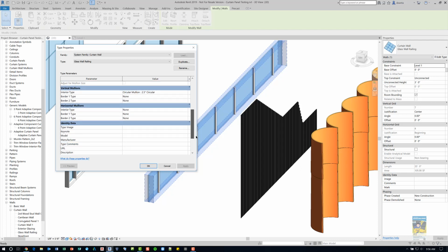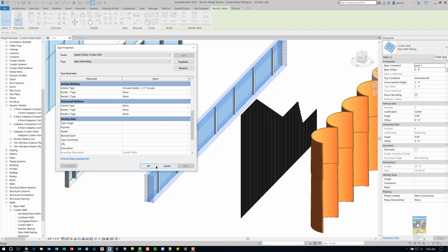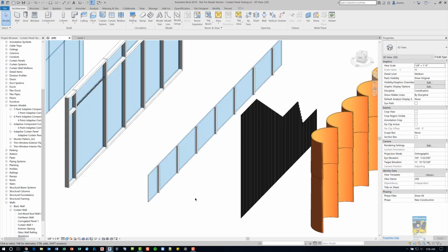So if you use this kind of approach and just specify this information, you could actually make it act like a glass wall with railings to a degree. You can also create a generic family that is wall-based with an opening that you can also insert and nest in a family that looks like a railing, and then when you place it on the wall, it cuts into the wall just like doors and windows, and you can place that quote-unquote baluster wherever you need, and then organize it accordingly to make it look like a glass low wall with railings.